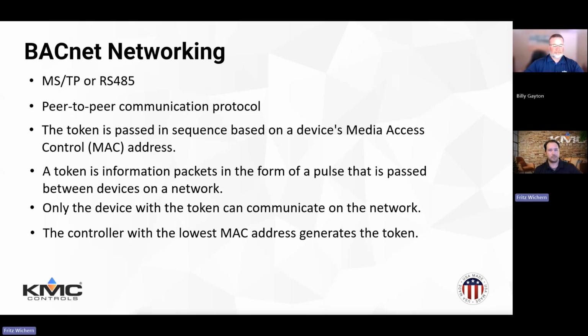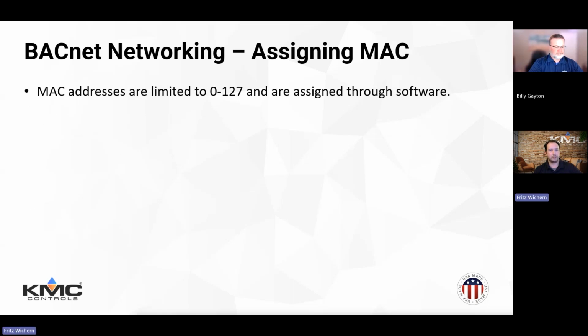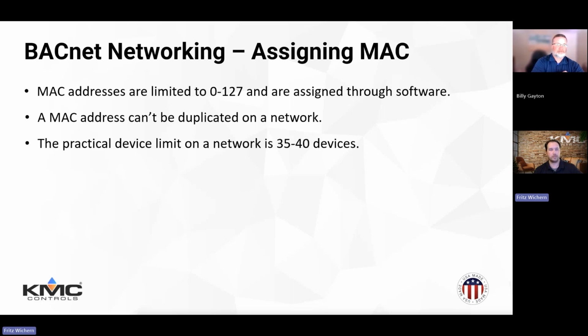All right, let's look at MAC addresses. We're limited to 0 to 127. You can go up to 255, but 128 through 255 are slave devices, and KMC doesn't use slave devices. All our devices are set up as master. A MAC address can't be duplicated on a network segment.